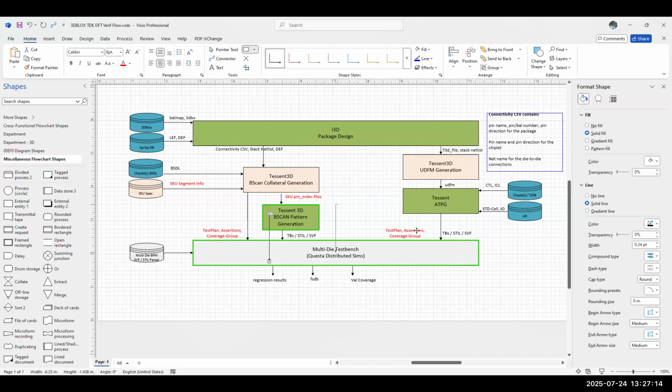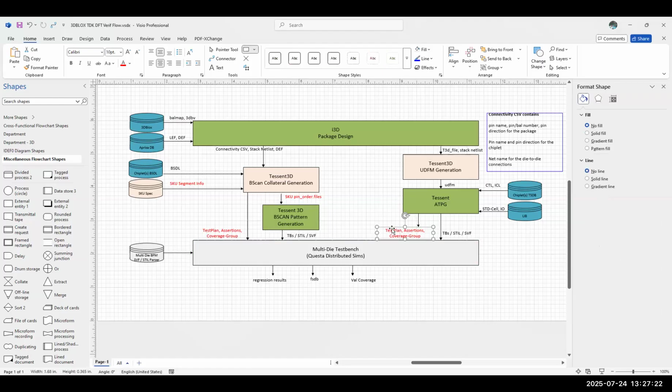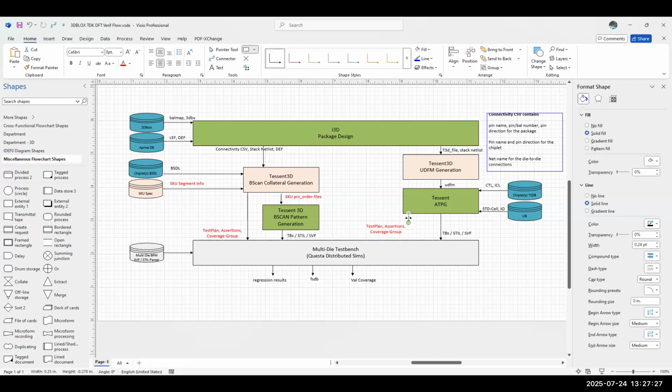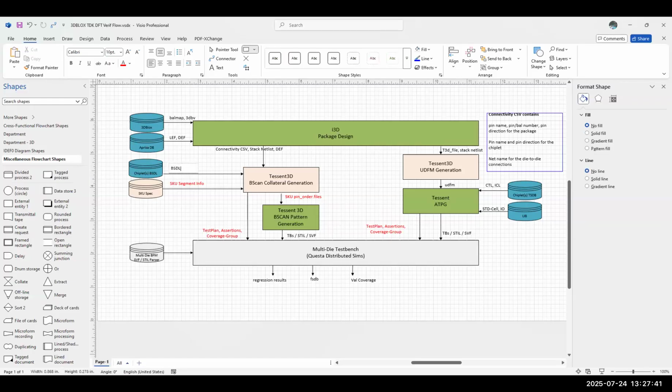And again, there would be some type of mechanism where you'd have to provide the patterns, unless it's totally BIST, then you just run it and you get a pass fail. You would need to provide some kind of patterns that are going to do the different types of tests. So I think the way the industry is going is you're pretty much using IJTAG to test everything.